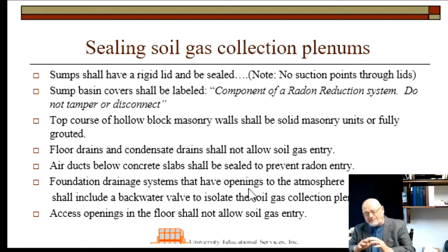Remember that the plenum, effectively that vapor barrier and everything below it, we'd like it to be airtight if we could possibly manage that. And so we need to consider things like sumps. They'll have a rigid lid, it'll be sealed. We can go through a number of things.